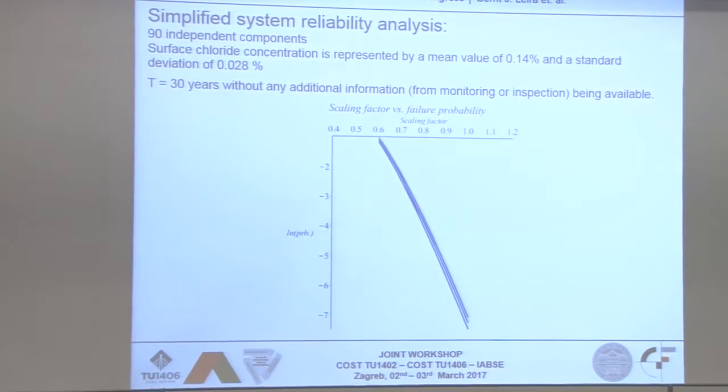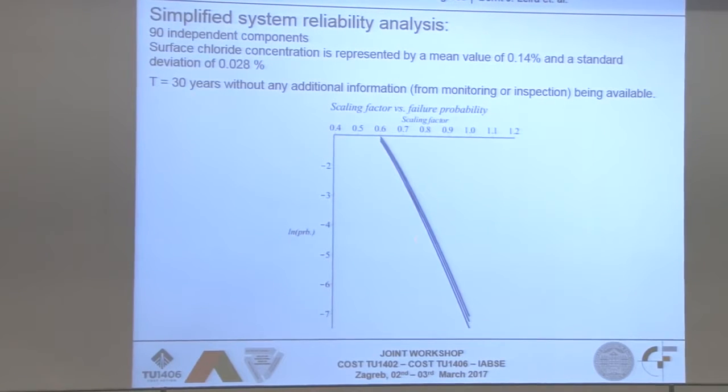That means you do simulations here, so you save time because you can tell what's happening at the so-called scaling factor lambda equal to 1, which corresponds to the true failure function. So this is a sort of enhanced Monte Carlo, where you save computation time by simulating here, while you predict what's happening here. Typically you can save computation times by a factor of 10, for the case we are looking at here.